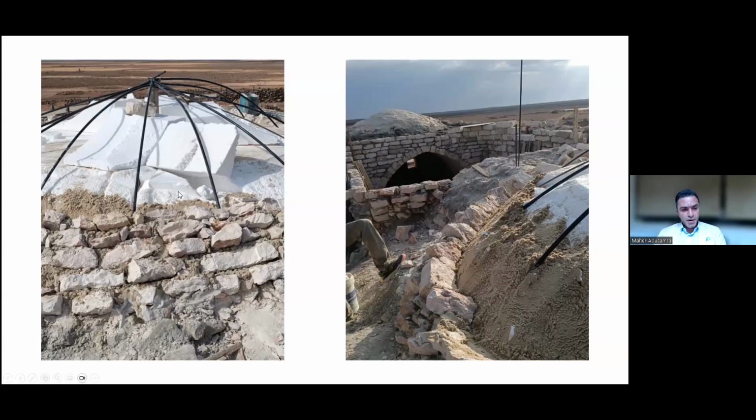But here, the upper third of the dome is not easy, because this stone is not stacking with the mortar, and we use silica with the lime. So what we did here, we invented something to have the upper part of the dome as a foam formwork. We hired the scaffolding to that level, which we couldn't complete or continue the construction, and put some sand and foam to get that.